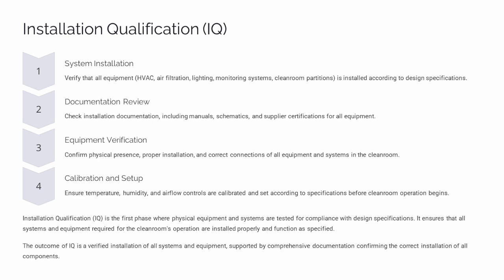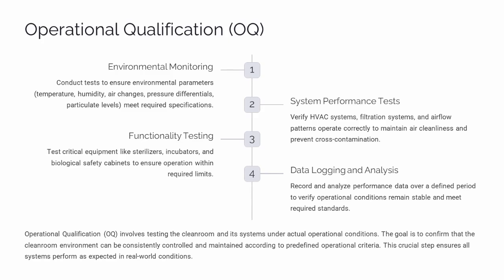IQ is a verified installation of all systems and equipment, supported by comprehensive documentation confirming the installation of all components. Operational qualification, OQ, involves testing the cleanroom and its systems under actual operational conditions. The goal is to confirm that the cleanroom environment can be consistently controlled and maintained according to predefined operational criteria. This crucial step ensures all systems perform as expected in real-world conditions. It includes environmental monitoring, system performance tests, functionality testing, and data logging and analysis to ensure operational parameters remain stable